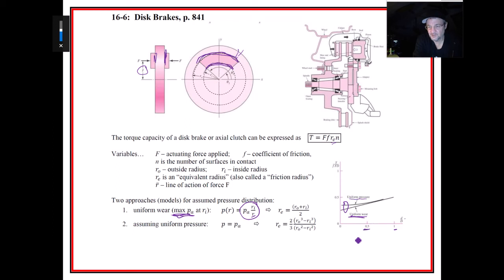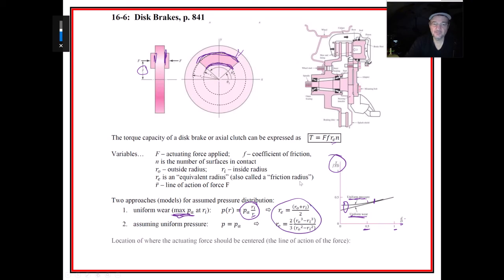As we're going up, so like maybe they're 1/2 of each other, right? The inside diameter is 1/2 of the outside diameter. You can see that anything below that, there's a gap right in here, so that confirms our suspicion that uniform pressure is going to give a better torque than uniform wear. But you could also see as those two things start to get closer to each other, it starts to not matter. And once again, that's just graphing out these things right here, right? That's the concept right up here.